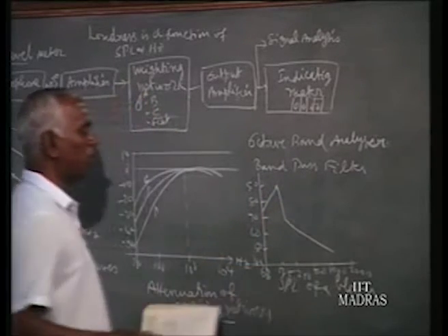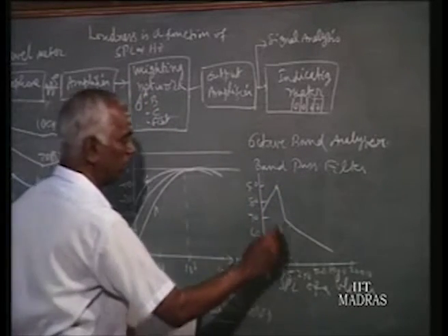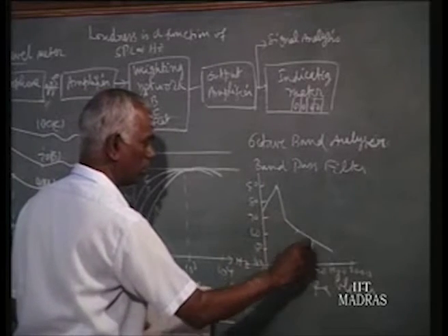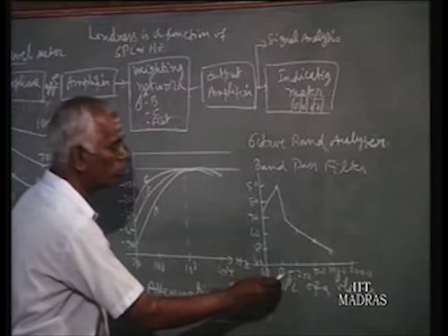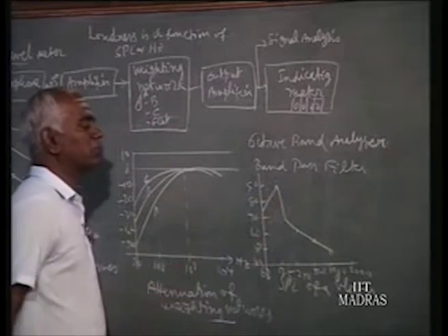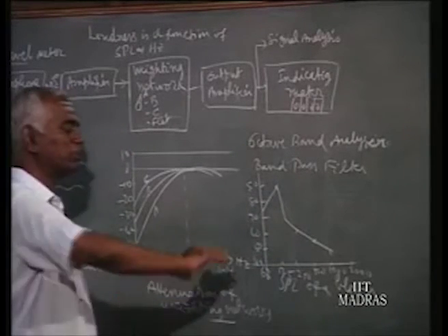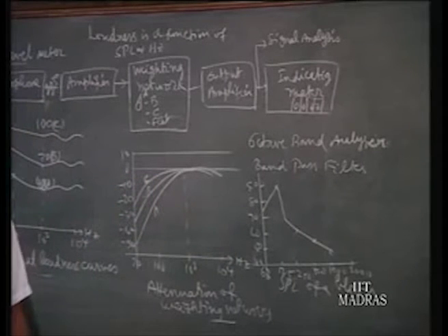So this is the plot of the different center frequency. You got this plot. So from here we know that at 125 hertz it produces the maximum noise. Probably 125 hertz may be a rotating speed of a gear machine.